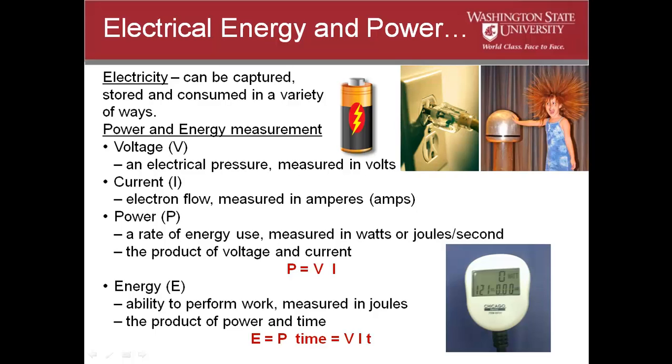As shown here, the display also shows power, but because it's intended to measure higher power items, it does not display a low power reading with the necessary significant digits. It will be necessary to use the voltage and current readings to get more precise results for our purposes. Power. The calculation is the result of the product of voltage and current. The resulting units are in joules per second, and as a rate of change shown by the units, it helps to see that the energy is provided and consumed at a periodic rate.